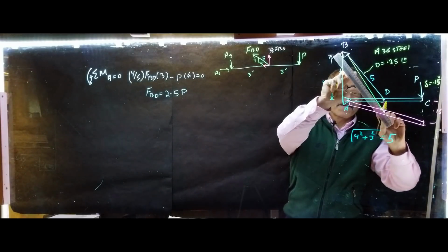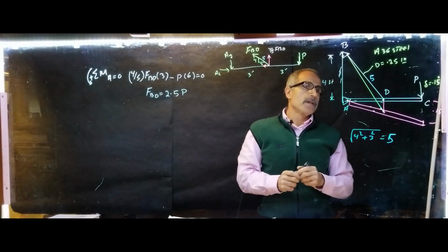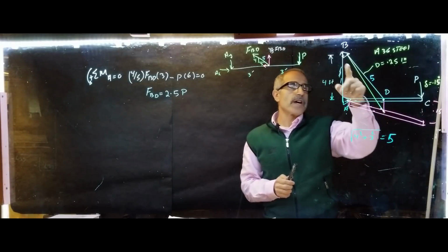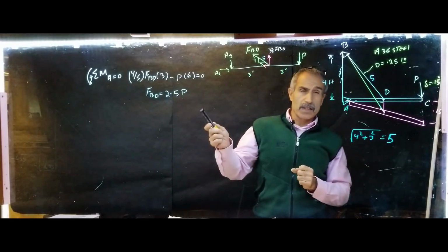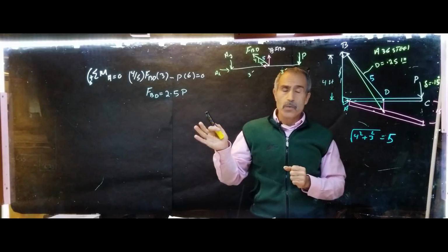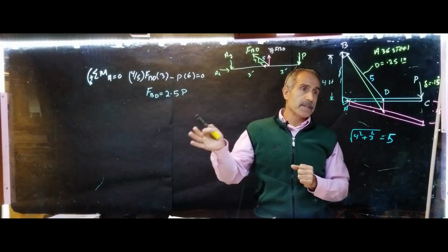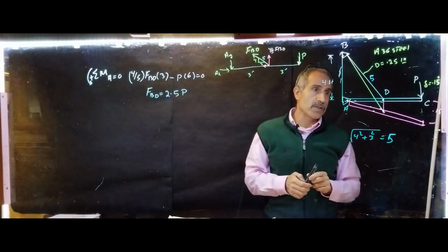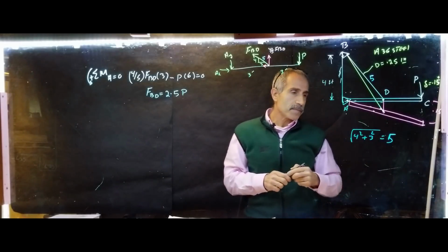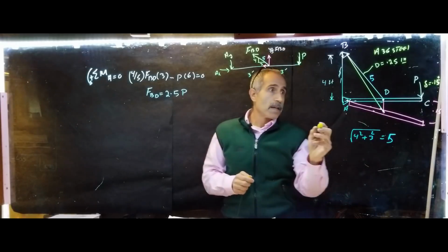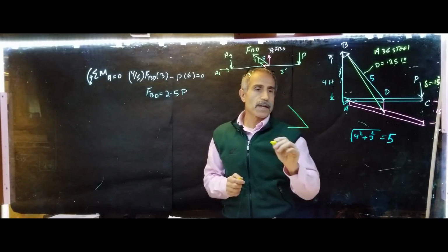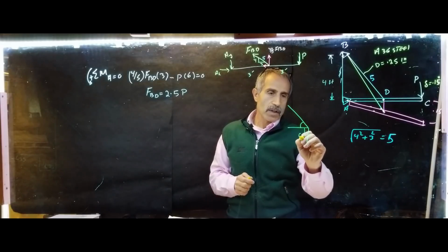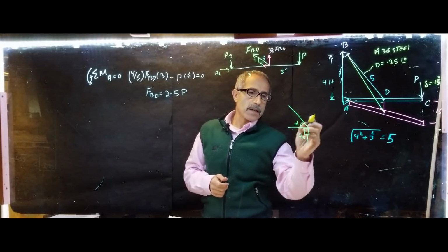All right, we're cooking. Now the new cable, based on this load, stretches up like here, and I end up with this triangle. Last semester we talked about the cosine law, and based on the cosine law we can figure out the length of the cable, how much it has stretched. First, let's figure out this angle here. We have the cable going like this, and we know this angle is 90 degrees. So I have 90 plus this angle.